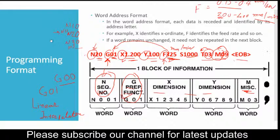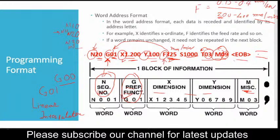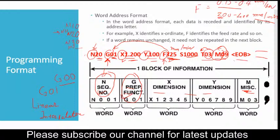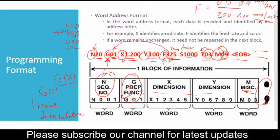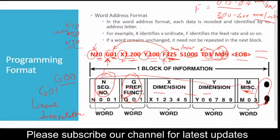See, if we write a program on line 1 and we want to jump to line 2, we will press the input button in the machine controller that I have stated. It is a yellow color button. It is the only yellow color button. Previously, we were writing this symbol so that we can enter a new line, so that once this symbol is read by the machine, it will interpret that this block is over. This entire line is said to be a single block.